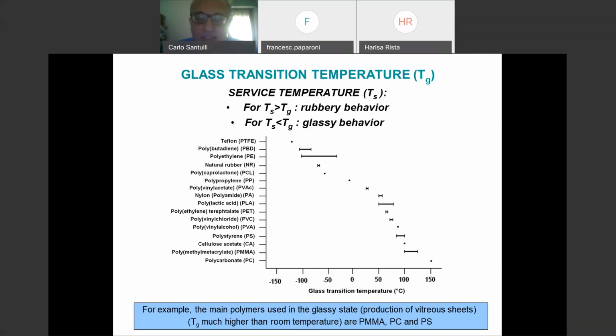And you may consider that it needs an additive in order to be able to get also to temperatures below zero, well below zero, also because it's used also for car bumpers in combination with glass fibers, etc. So as the matrix for glass fiber composites.